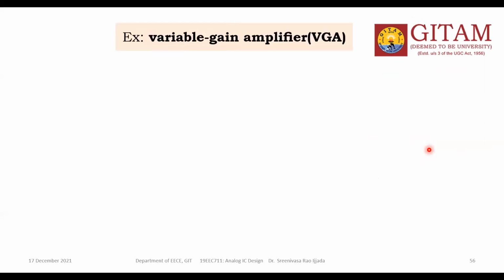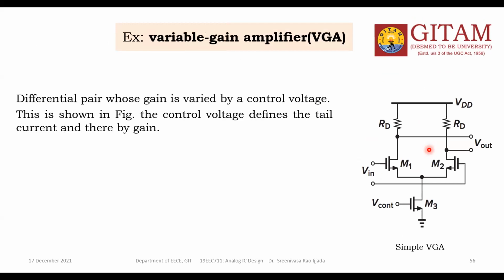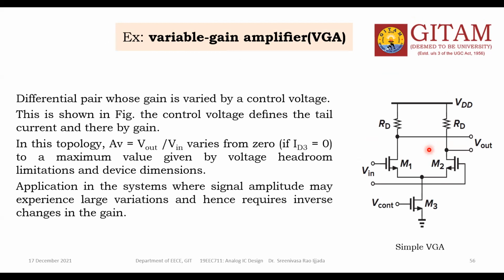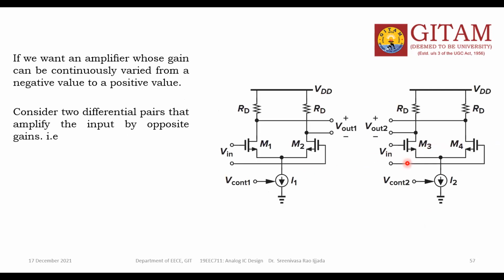Today I already repeated once again about the Gilbert cell. So the Gilbert cell explanation starts with the VGA. In the VGA, what is the difference? Whatever the transistor whose gate carries the Vcont value, the other gate is connected to a fixed voltage, because that transistor should be operated in saturation. These are two different ways. So this will give the output Vout1, and this will give Vout2.